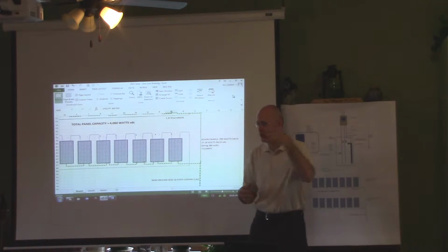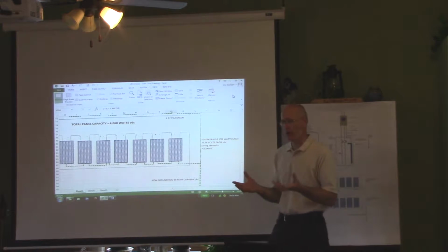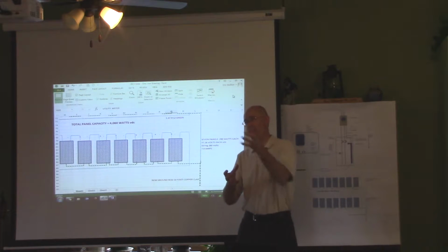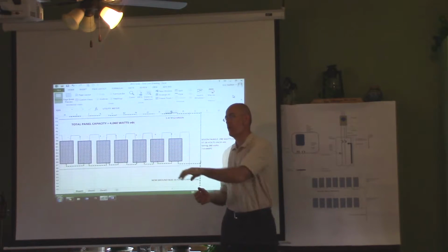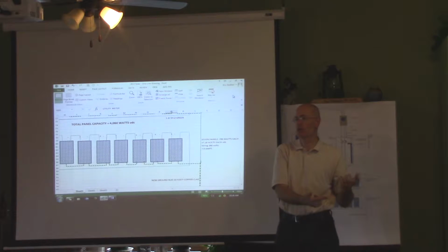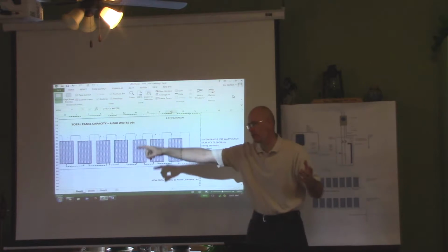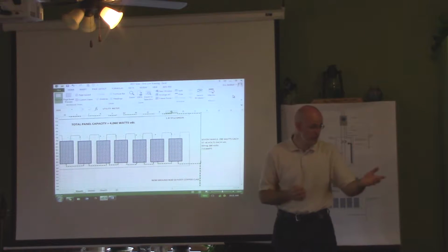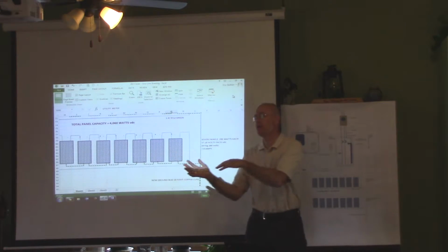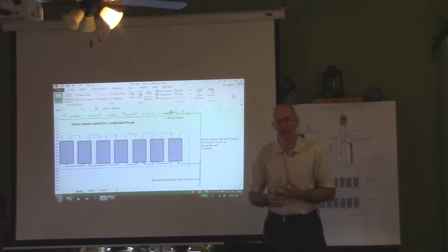And the opposite of direct current would be alternating current. What does that look like in a wire? Direct current are the electrons moving from atom to atom to atom down the wire. And they keep moving that way until they get to their load, and then they come back and neutralize themselves on the negative terminal of the car battery or whatever's producing. So it's a direct path. Alternating current is what you get from your outlet. That's where the electrons go this way, then back, this way, and then back, 60 times a second in the United States. Europe's 50 in many places in Europe.